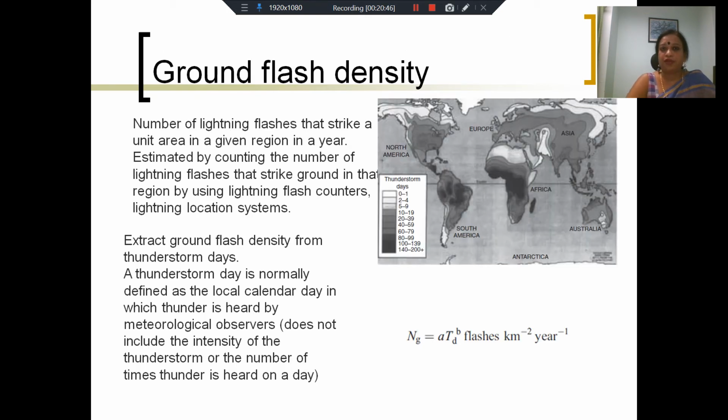Now, therefore, when we want to design a power system, the first thing we have to figure out is we have no control over the lightning. We do not have any control over the lightning magnitudes. We do not have any control over how many times lightning may strike. But we can estimate that before we design the system, because we have what is called the isokeraunic map of